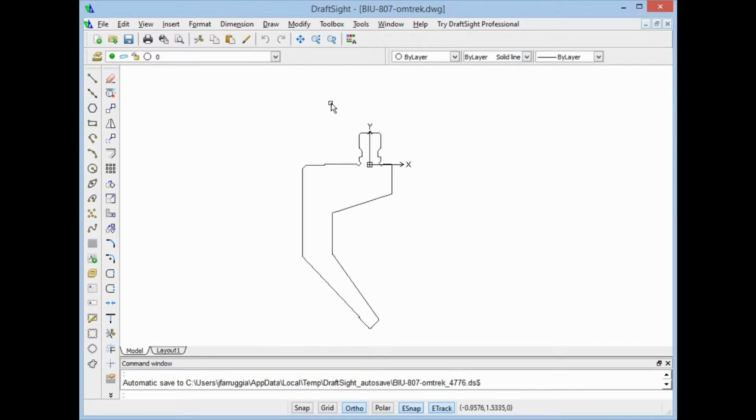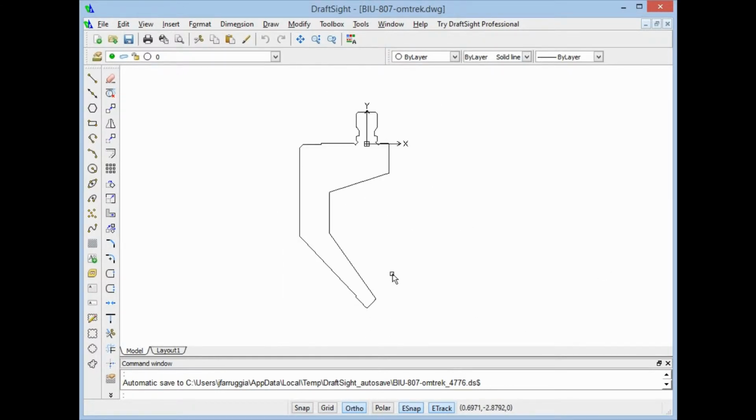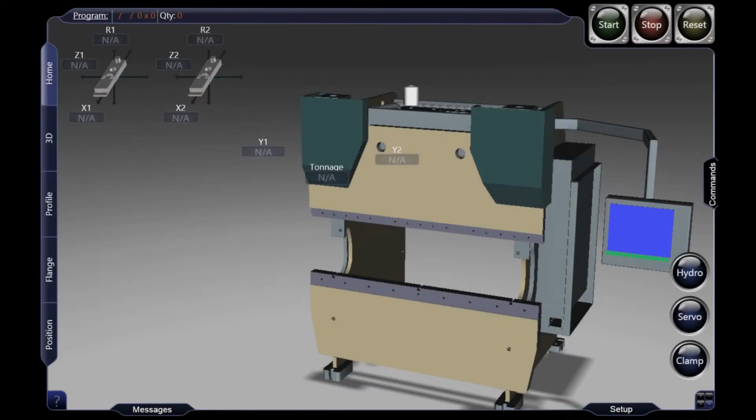Very important. And if you do get a file from a manufacturer, ensure that it's in inch, especially if your Vision is set to inch. If you get a metric one, it's going to import at the wrong size. So prepare your file here, and we'll get ready here, and I'll show you the several ways that we can add a tool to our Vision library.